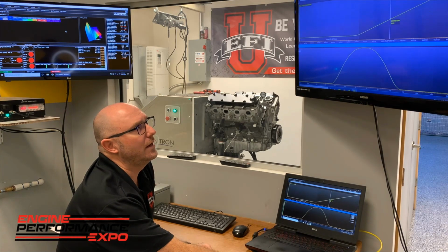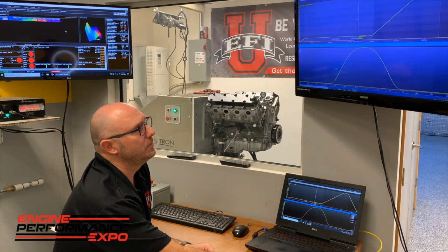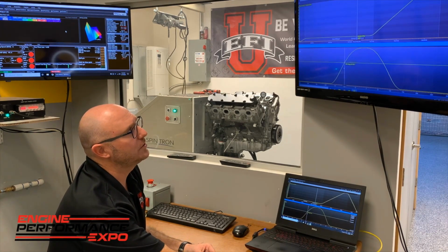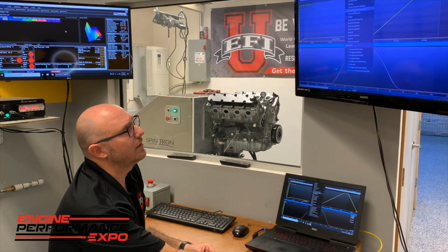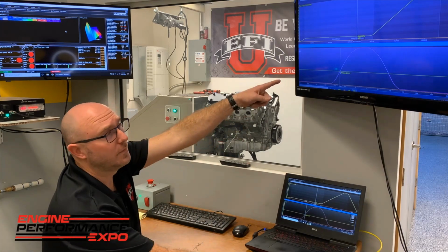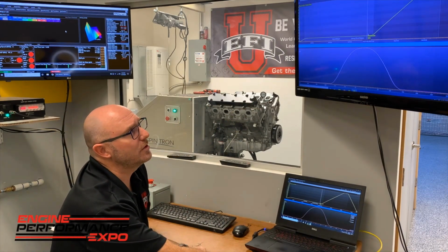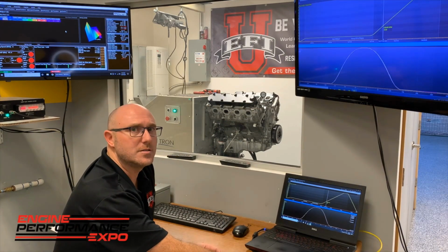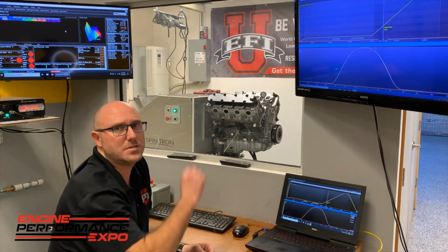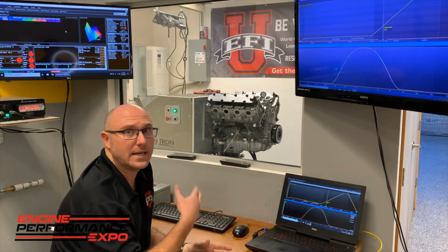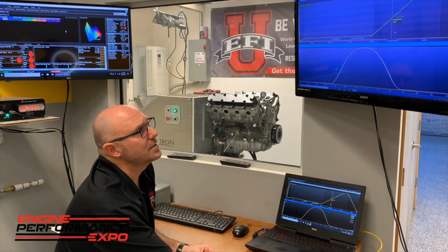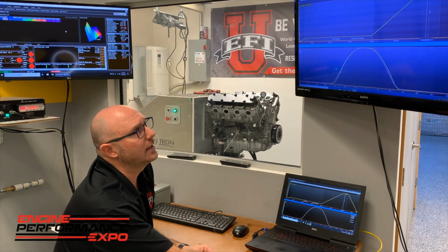So I can pick anywhere along the way. I can zoom in on that, zoom out on that. But what I'm going to do, I'm going to start here, and I'm going to make that 1,000 RPM my reference. I've now turned it purple, so that now as I sweep through the RPM range, I can see the difference between what the valvetrain was doing at that specific RPM versus what it was doing when there wasn't a lot of load on it, say at 1,000 RPM. So as I sweep through here, if I pick a spot like 6850, it's a nice easy spot.